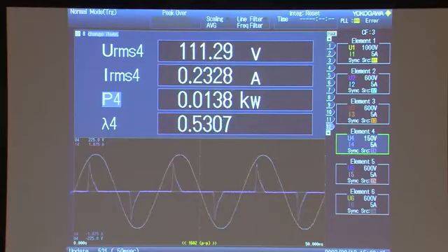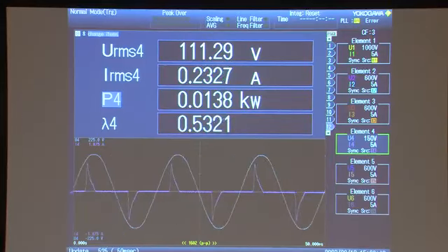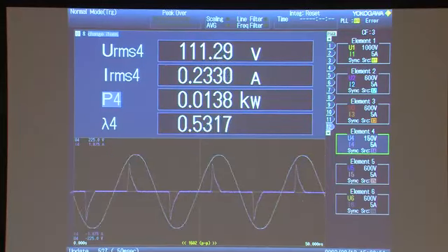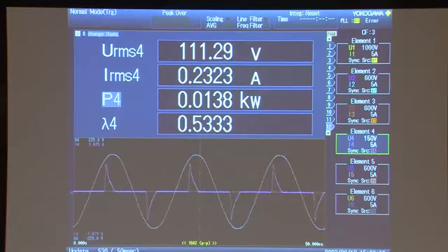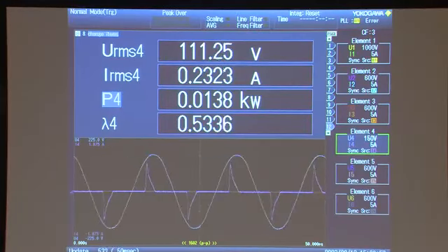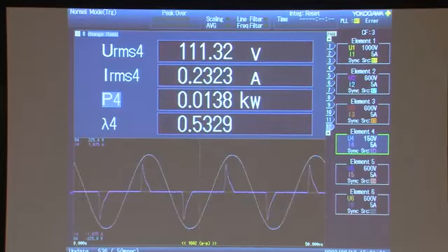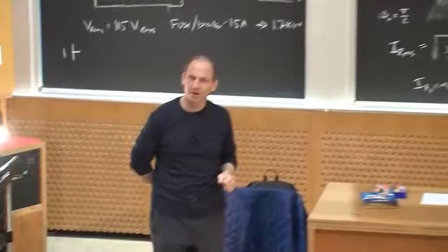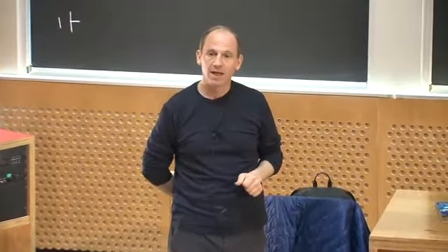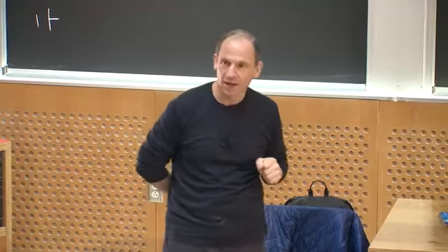So this leads to terrible power factor, and you can see that the power factor is only about 0.53, right? What that says is if you use lots of these bulbs, you're using up the capability of your source to deliver power. What that means is, while we're not measuring it here, you're dissipating more power in the wall wiring than you need to, okay?